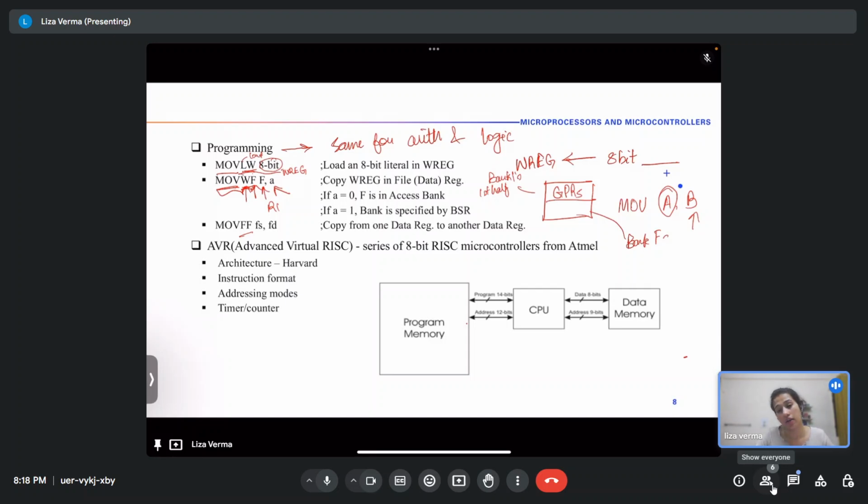So you can code them in a high level programming language, and these are available in different variants depending on the size of your flash, your program memory, size of your EEPROM, number of IO pins that are available, on-chip features, UART, and analog to digital converters.